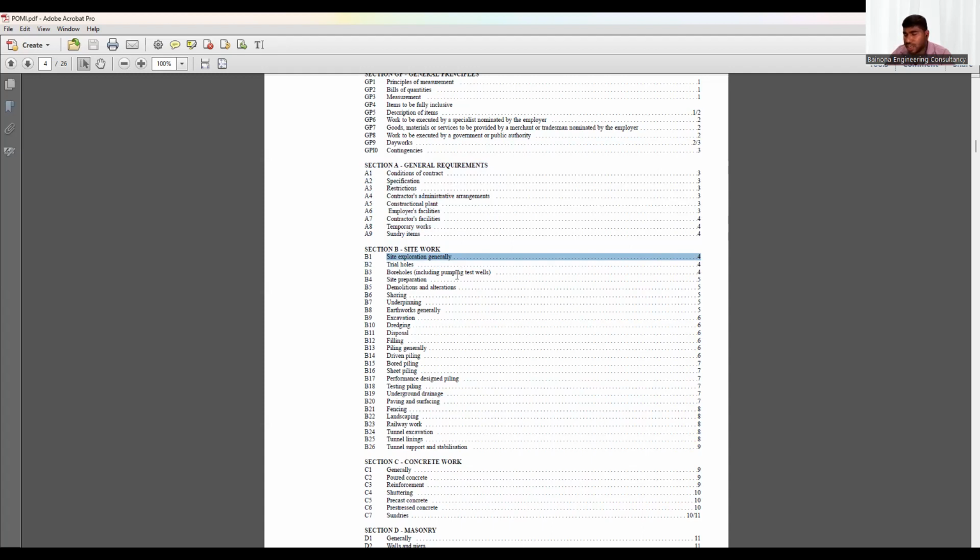First, you have to do the soil investigation. You have to bore the soil and understand the section of the existing soil conditions. How many meters you have of rock, how many meters you have of soil, and how many meters you have of hard rock. And when you encounter the water, these all will come under the soil investigation. That is one thing.